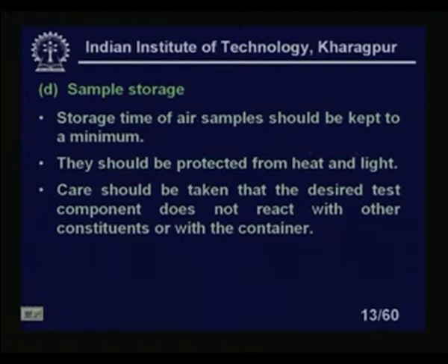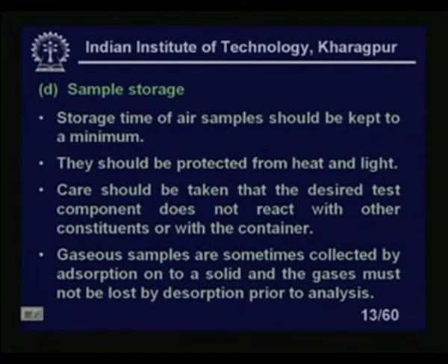Care should be taken that the desired test component does not react with the other constituents or with the container. So, the container should be sort of inert, probably made of glass or stainless steel, so that whatever the pollutants or gases are, they should not react with the container, okay, those things should be considered. Gaseous samples are sometimes collected by adsorption onto a solid, and the gases must not be lost by desorption prior to analysis. Okay.